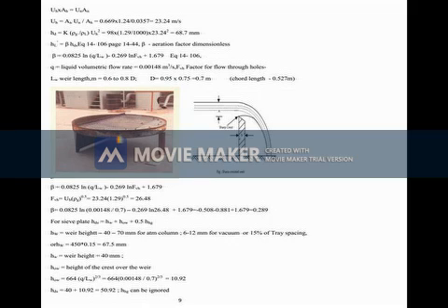From this, what you get is the chord length. To get the chord length only we are using it. This chord length will be the length of the weir. So you can assume some 70 to 80% of the diameter. If you are not very sure about it, you need not do this exercise. Here the tray layout is shown.